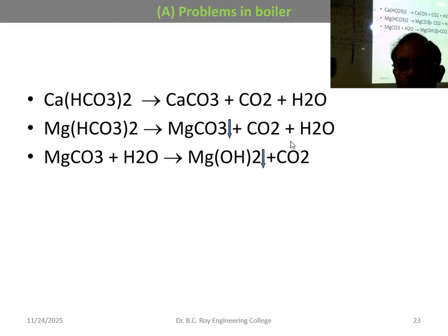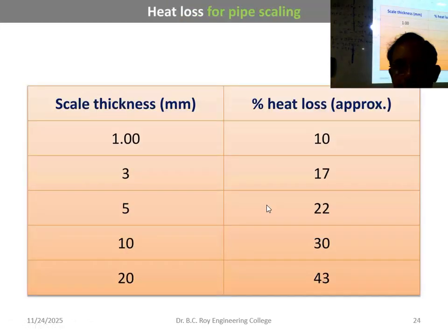So a problem in the boiler means this deposition is the problem. Whenever you boil this hard water, the temporary hard water becomes soft water. But what about the deposition of the salt? That will be there. It will give scaling. That is the problem related to boiler. Sir, does this deposit specifically? Yes, that is scale. It is called scale.